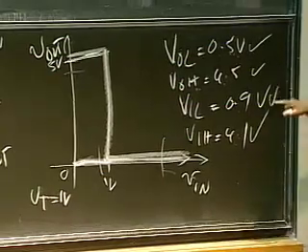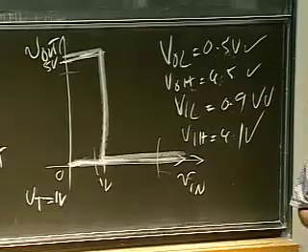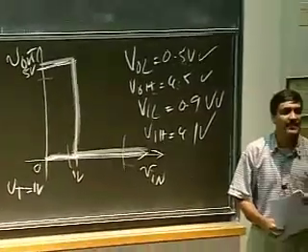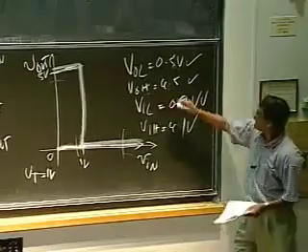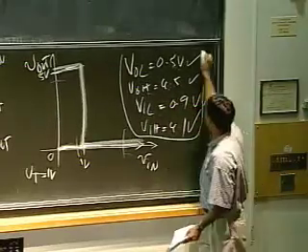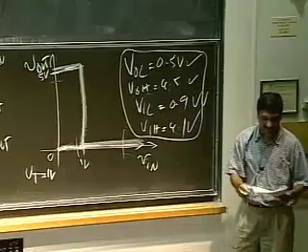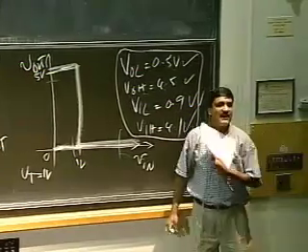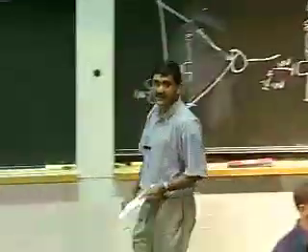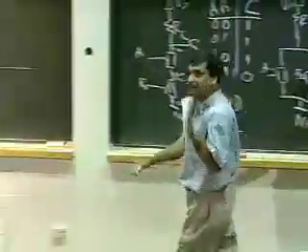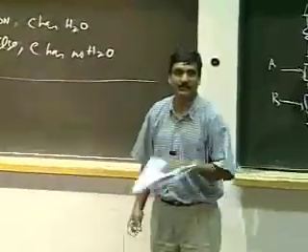So therefore, this inverter that I've designed for you here satisfies the static discipline, and this inverter can be used in circuits that conform, or other devices that conform to this value here. In your recitation, you will look at a slightly more detailed model of the switch, where the switch behaves like a resistor. Okay.